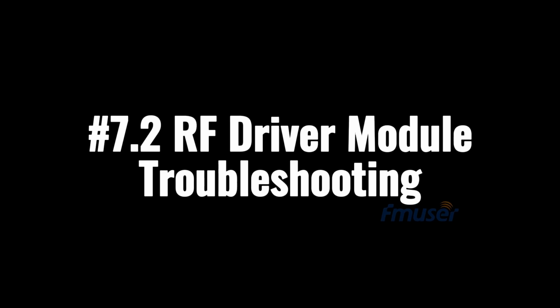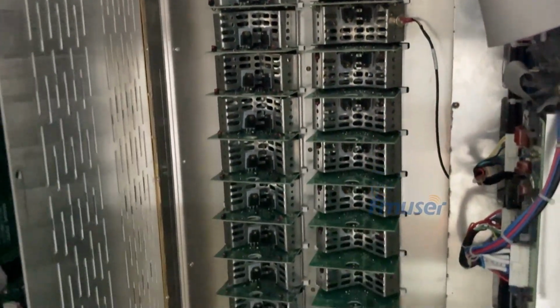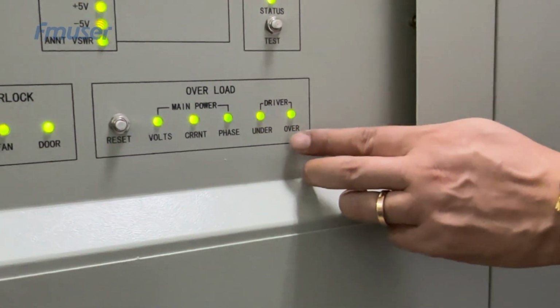The RF driver module troubleshooting. In the event that multiple power amplifier boards within an AM transmitter become damaged, the most likely cause can be attributed to voltage overload. To monitor the voltage status of the power amplifier board, the overload monitoring area includes 2 indicators labeled as under and over under the driver section. These indicators reflect the driving voltage condition of the power amplifier board.